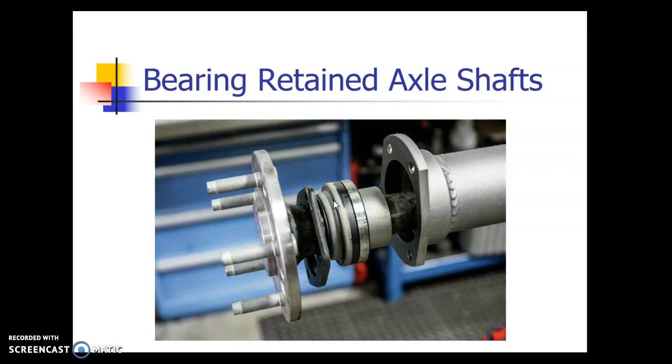So it kind of keeps that bearing from shifting, and it holds the axle assembly. Everything's kind of pressed together. Bearings pressed on the axle, retainers pressed onto the axle. This cover bolts onto the housing, and it kind of bolts everything in place. So if the bearing were to break, this axle could come flying out.